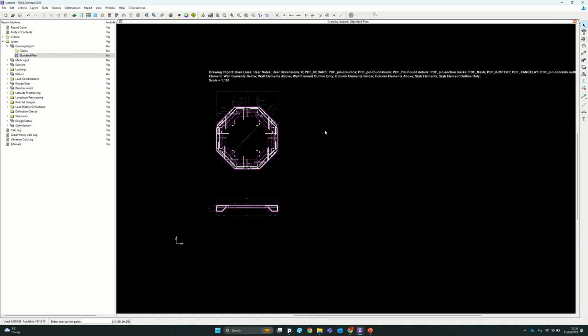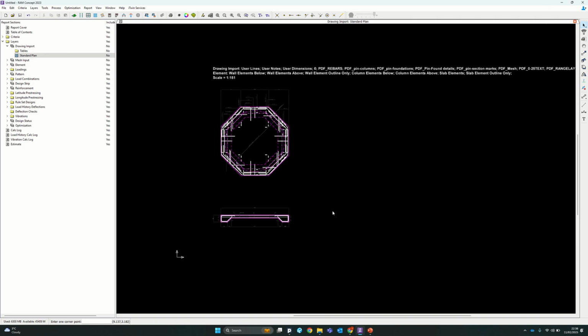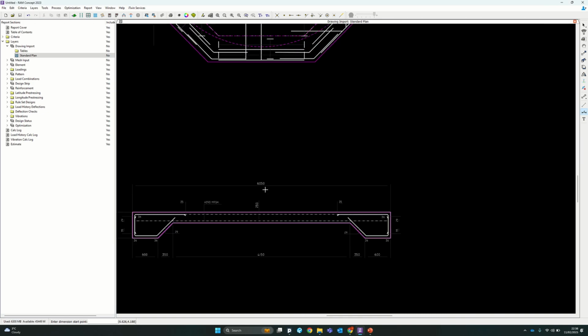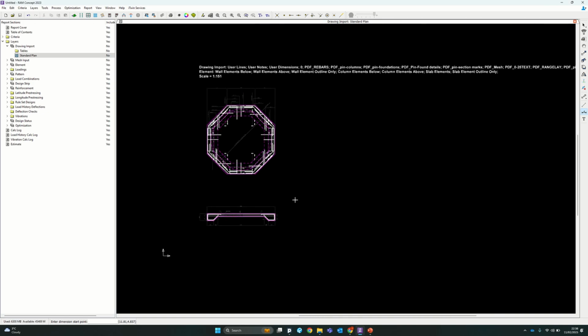There is actually a way within the import to specify scale and the units that you're using. Sometimes I've come across errors when importing CAD drawings based on the units. You have to make sure that the units are correct. If you were working with millimeters, import millimeters, that sort of thing. It's worth giving it a check when you come in, just to draw a line across and make sure what's on there is exactly what you have already dimensioned on your CAD drawing. Following that then, that's fixed into place.